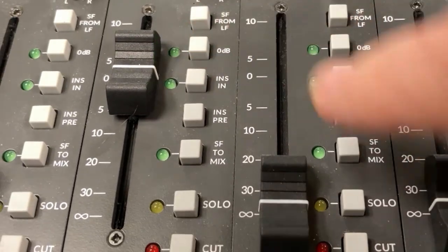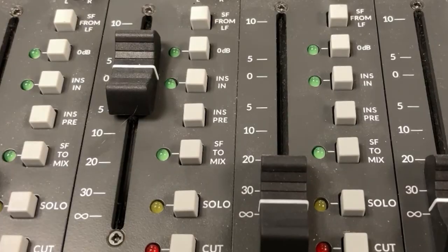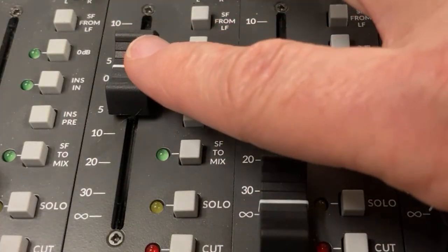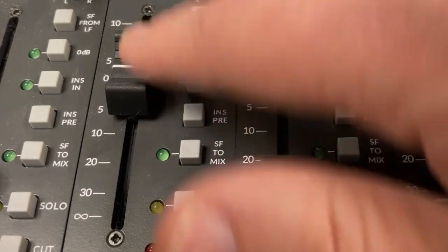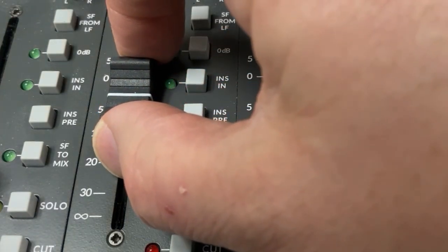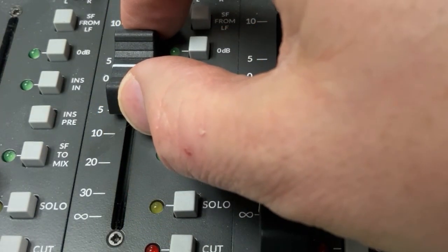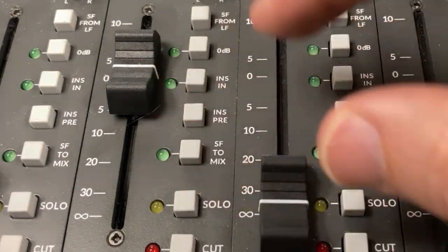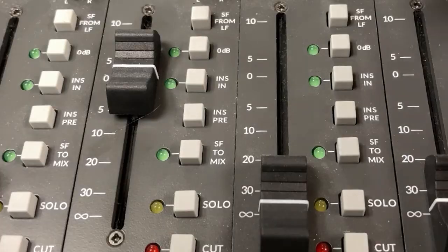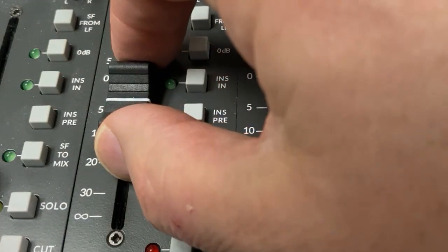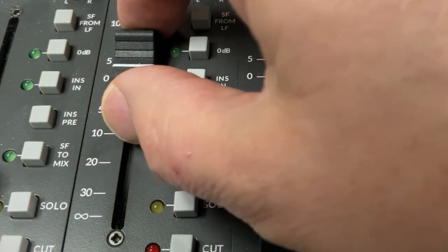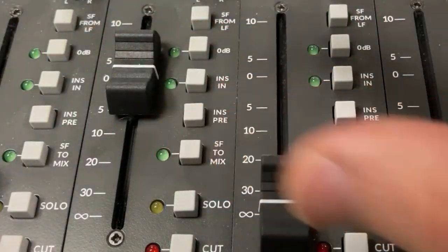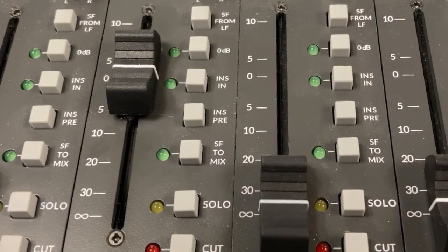So the whole point of having a fader is sort of twofold. One of them is if all of a sudden the signal gets really loud, rather than going up and reaching for the mic pre, I can just take this and turn this down a little bit. Or we can also sort of play with the saturation if we wanted to. So we can turn the mic pre up a little further and turn the gain down to make up for it. Using the fader is a better approach, in my opinion. So with the small fader, we're just letting the signal pass through.